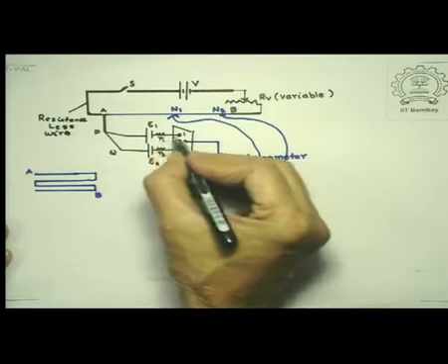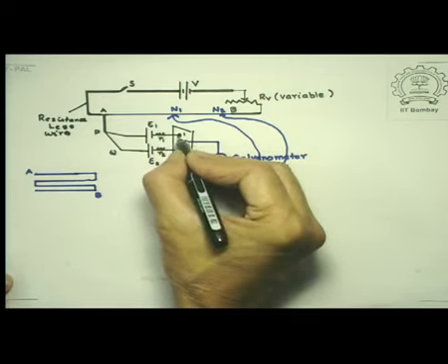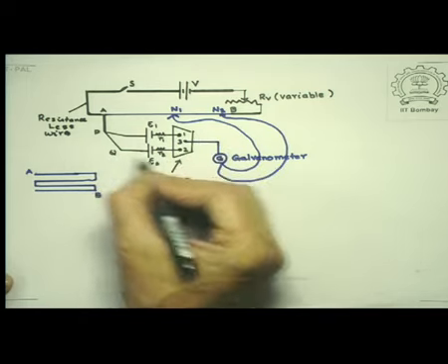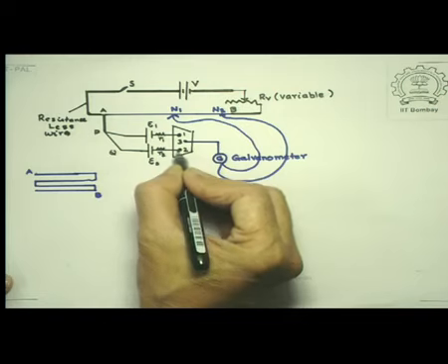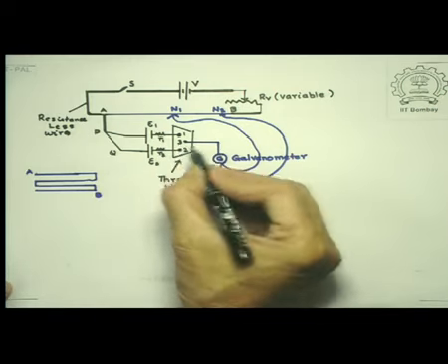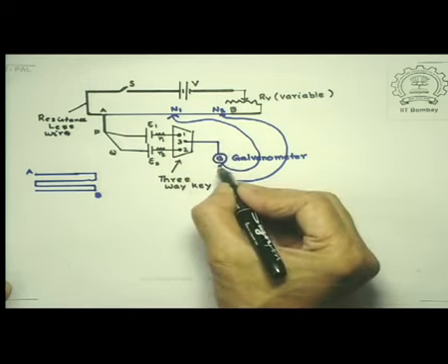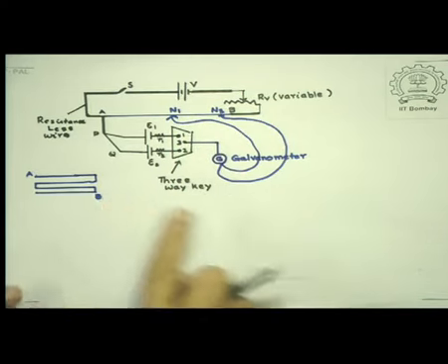The EMF source number 1 is connected to a three-way switch to, let us say, point number 1, and similarly the source 2 is connected to the second point of the three-way key, and there is a common point 3 which is connected to a galvanometer and to a wire which can slide over AB.